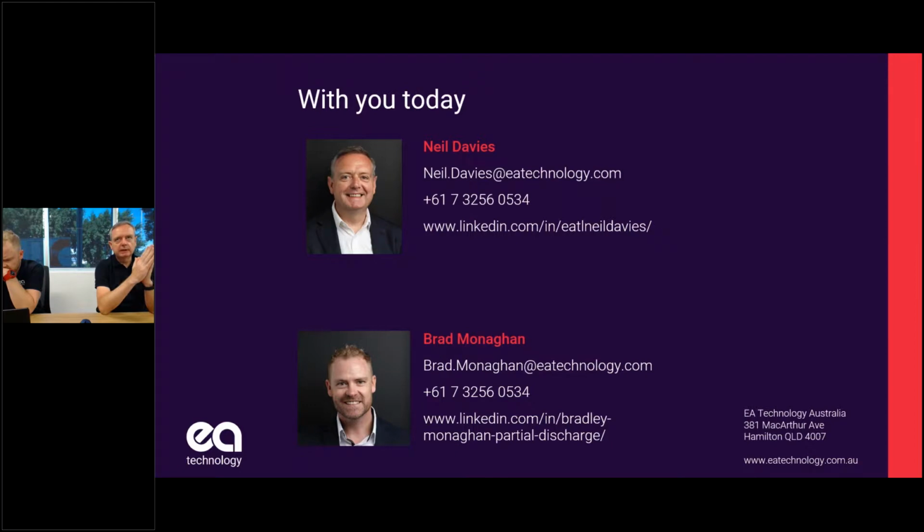On the PILC cable example we showed, it was a relatively clean earth, so 1.4 kilometers up, and we were finding it 56% up. So 700 and some meters up, we were able to see it. XLPE, absolutely, you'll find that, and further along. We typically say 2 to 3 kilometers, maybe 4 kilometers on a quiet cable.